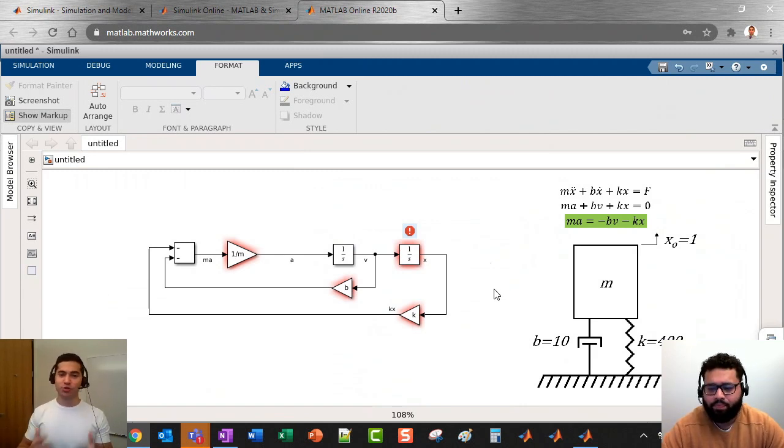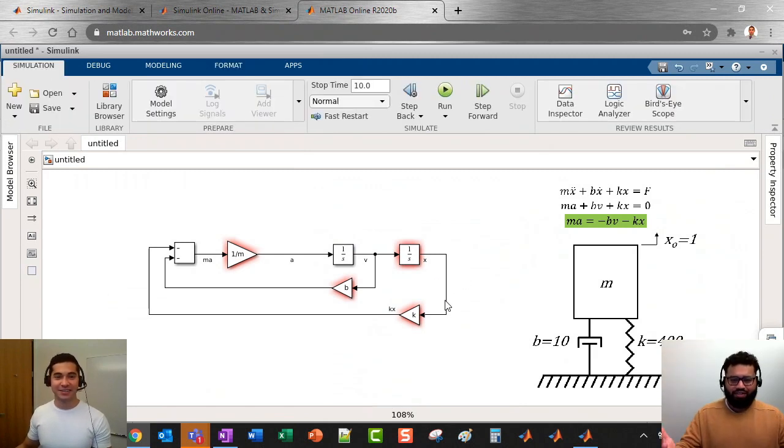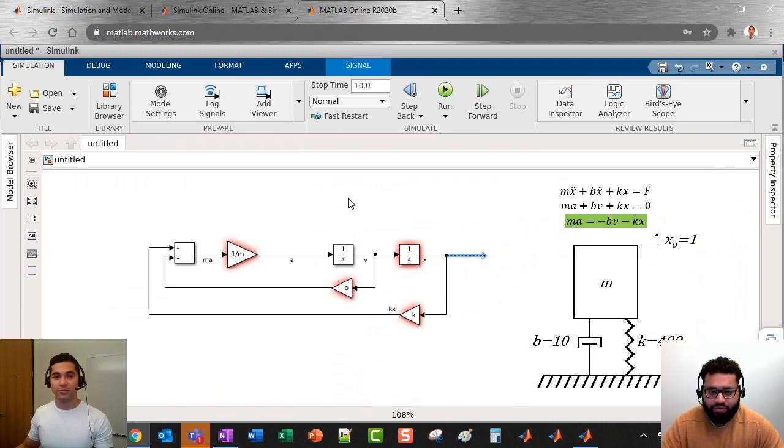All right, Connell, how do we visualize this data that we're going to get out of the system? Oh, this is my favorite part. You can use the Simulink Data Inspector, or you can use things called scopes. If you click on a particular signal, you have the ability to log it, as Ed's doing on the screen, or you can add it into a scope.